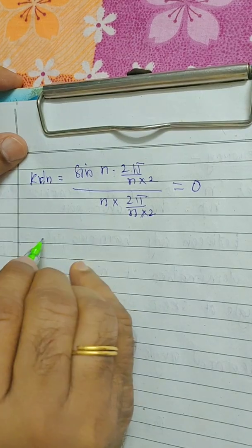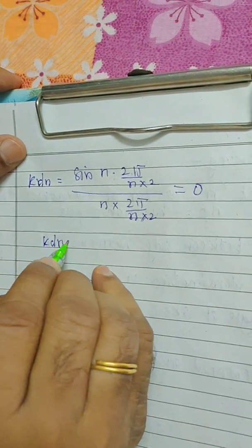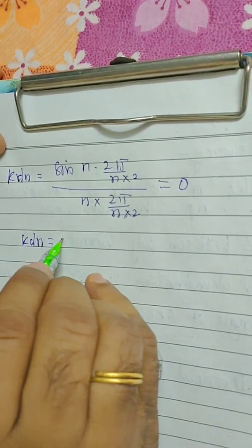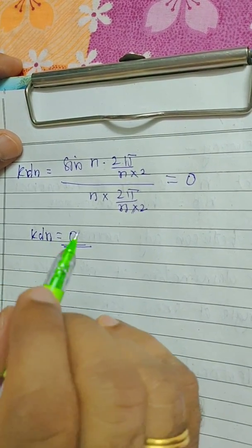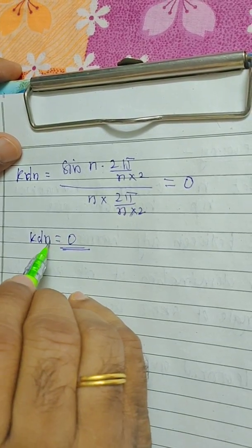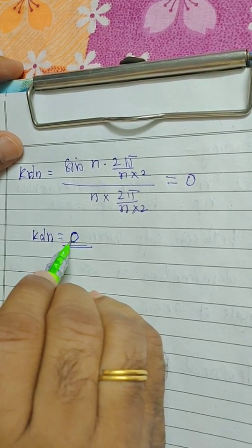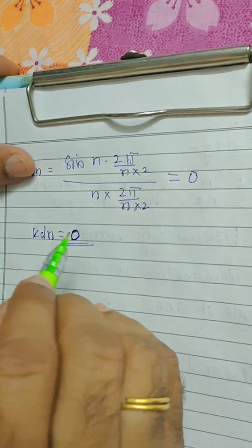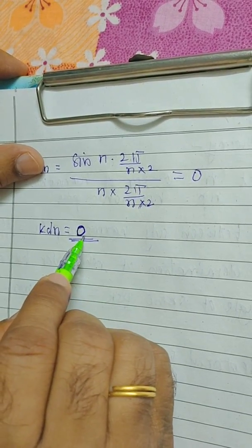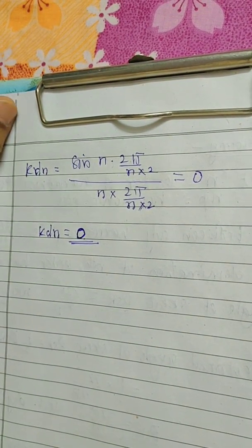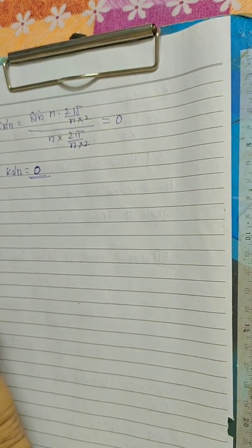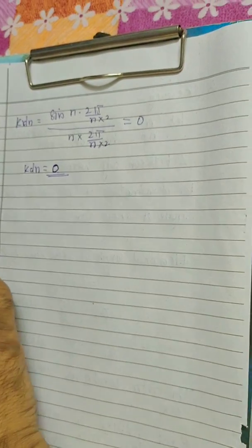So from above it is clear that the distribution factor for nth order harmonics is 0, and as the EMF induced in the rotor is directly proportional to the distribution factor, the harmonic EMF induced in the rotor winding is 0, so no harmonic current is developed, and we can say no harmonic torque is developed.